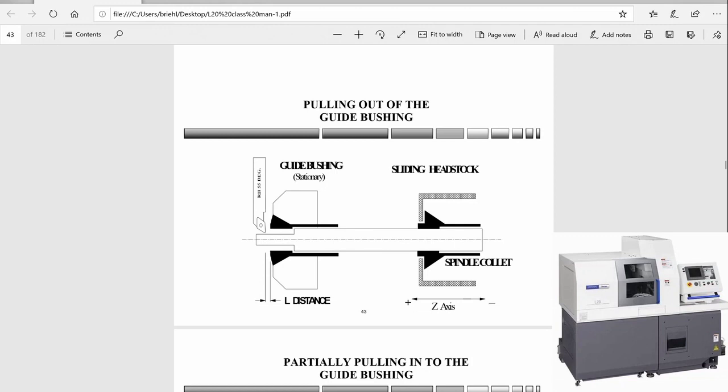We must follow the rules of Swiss-style machining when planning our process. ID work is done first on the main spindle. We also need to process the part in a manner that always allows for plenty of bar stock to contact the land of the guide bushing. A standard TD25NS guide bushing has roughly 3/4 of an inch of land, plus there is an additional 3 mm distance from theoretical Z0 to the face of the guide bushing. For this reason, we never want to pull the material back into the guide bushing more than 3/4 of an inch.